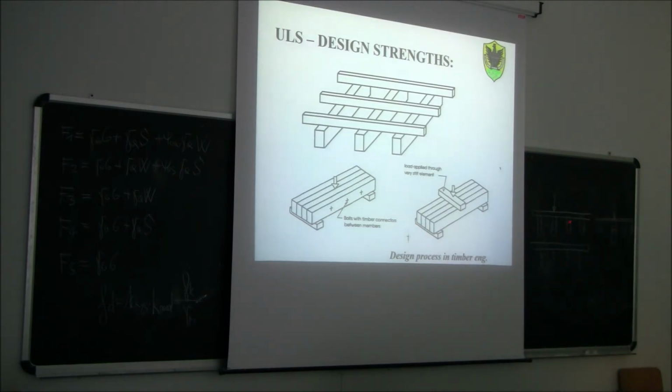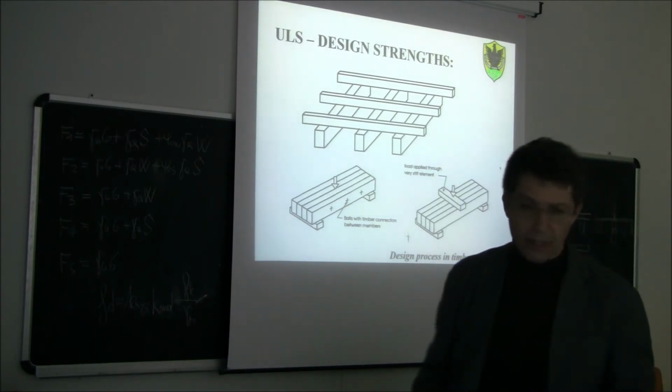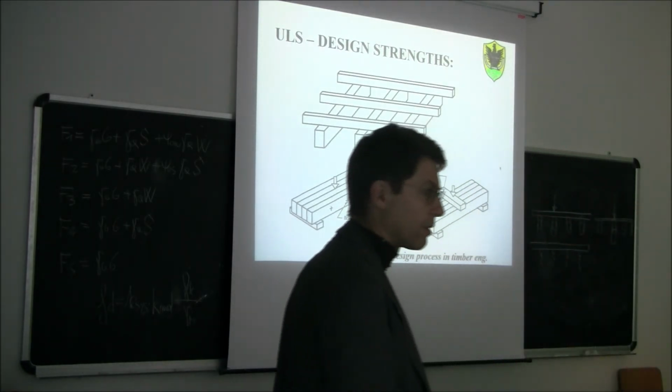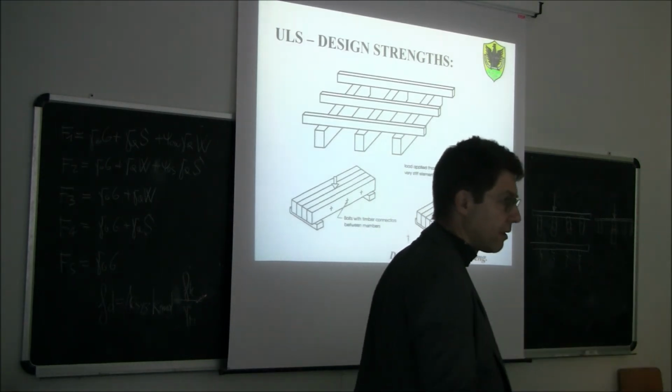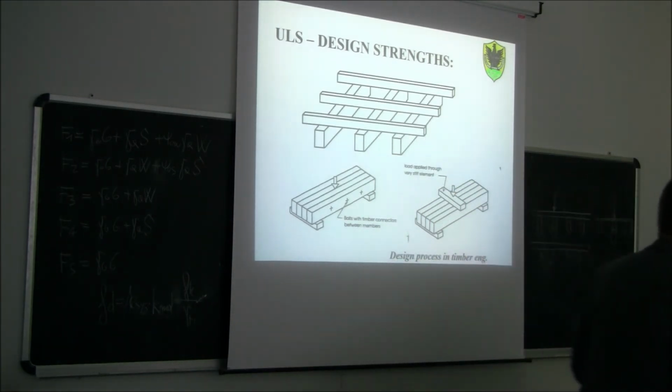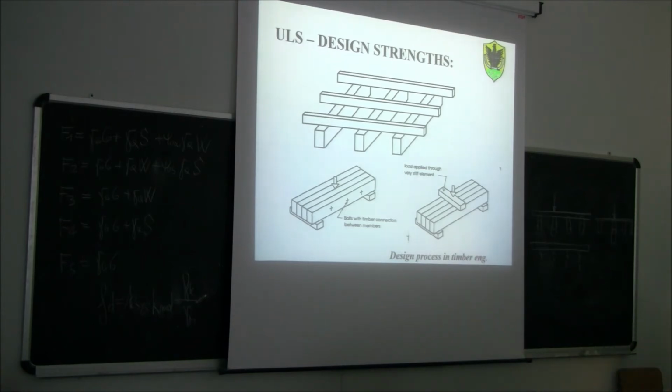So in this case, just remember that in timber we can have a significant variability of properties between the different beams. If you remember, we have a large scatter of results, meaning that with 4 beams, we may have one beam very strong, another so-so, another middle, another very low. Because of the scatter of the material, it's not very stiff.